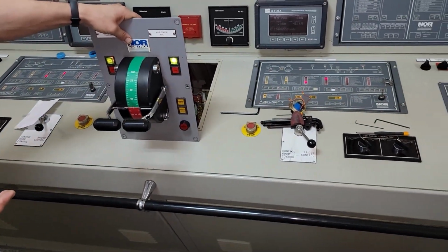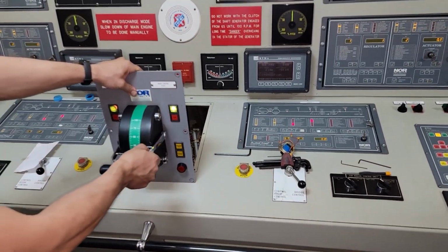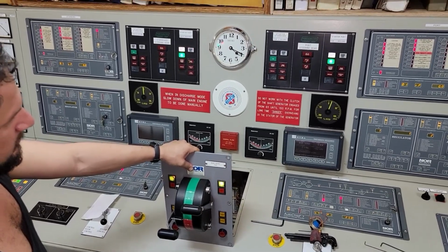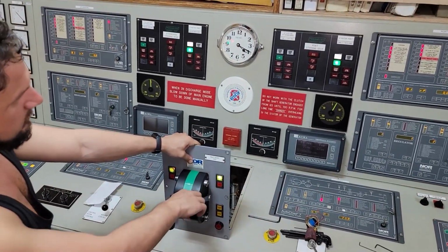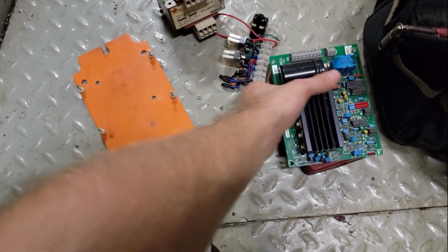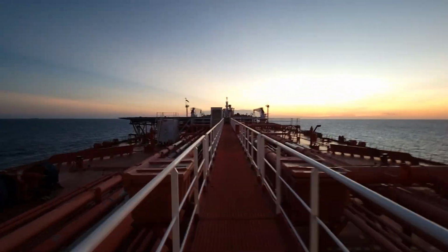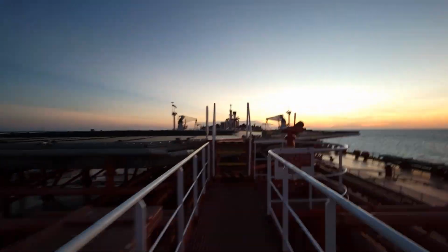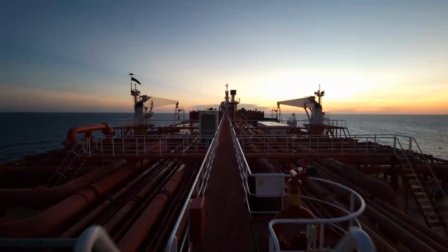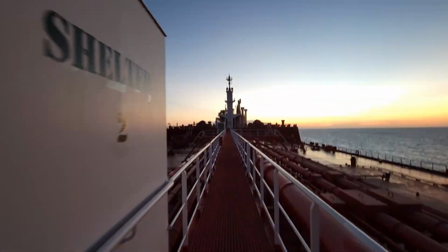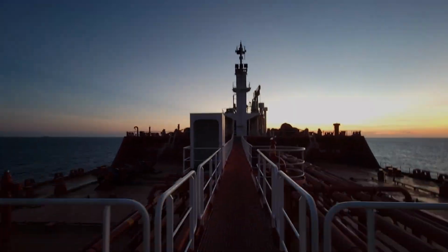Adjusting the potentiometer took a little time, and as a result the system worked properly. 2 months later we received spare parts and a new driver was installed in its original place. Also at the beginning of this contract, one bow thruster and one stern thruster were faulty. The problem was also in signal converters. After replacing them, everything worked properly.